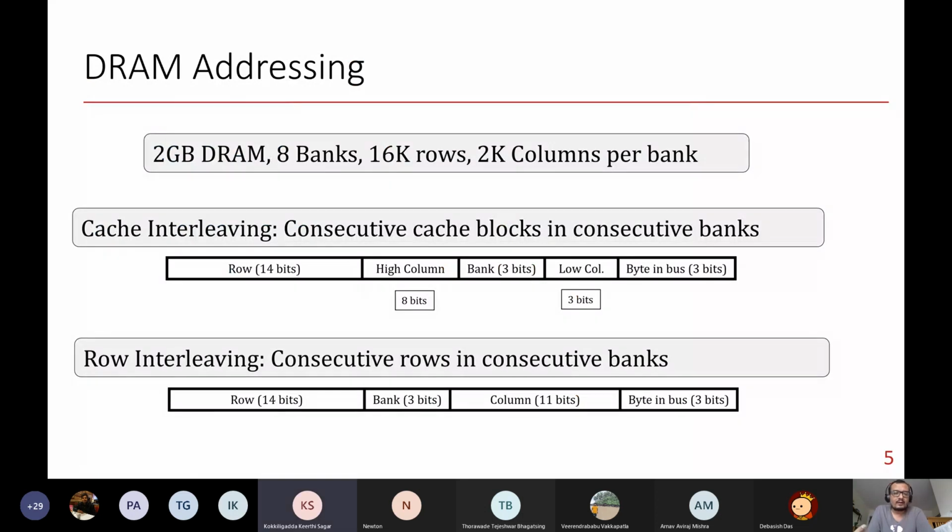If you look at current machines, they don't have any fixed kind of address mapping. Instead, similar to the LLC indexing mapping that we discussed, they use some kind of hash that takes bits from here and there. Even at the DRAM level, you don't use something very specific or deterministic. You put an XOR here and there and make sure the requests are scattered across different banks and rows, so that some form of parallelism can be exploited.